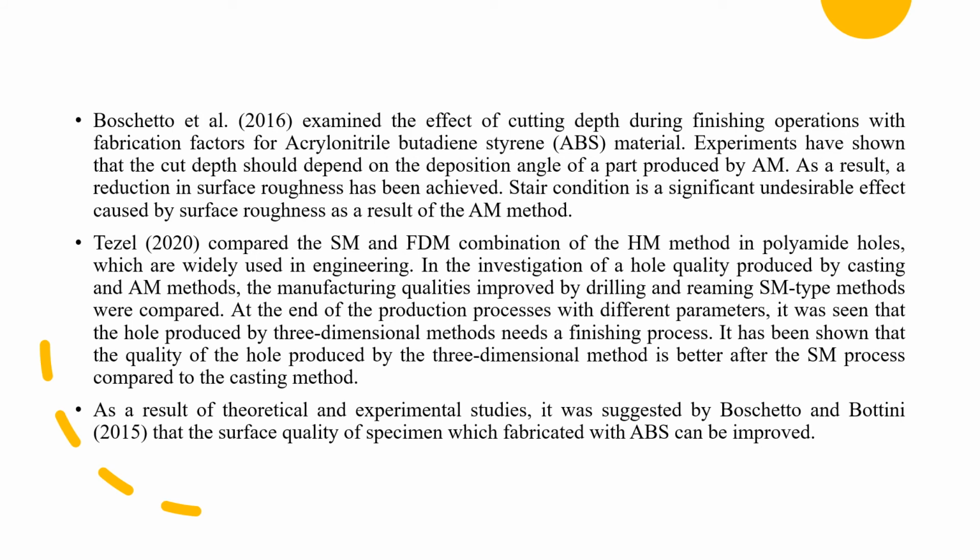Boschetto et al. examined the effect of cutting depth during finishing operations with fabrication factors for acrylonitrile butadiene styrene material. Experiments have shown that the cut depth should depend on the deposition angle of a part produced by AM. As a result, a reduction in surface roughness has been achieved. The stair-step effect is a significant undesirable effect caused by surface roughness as a result of the AM method.